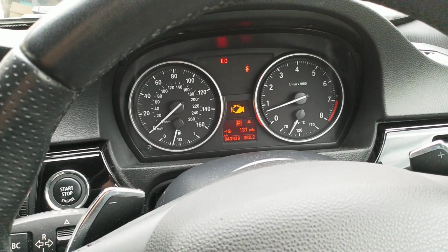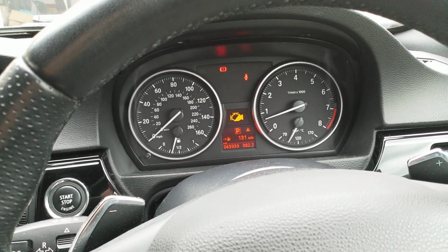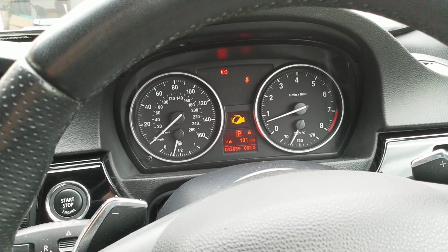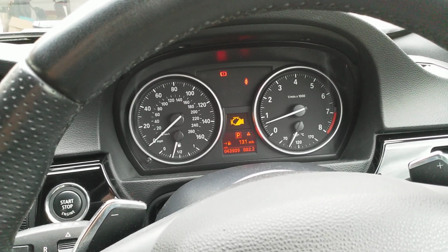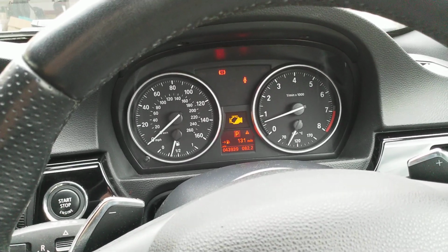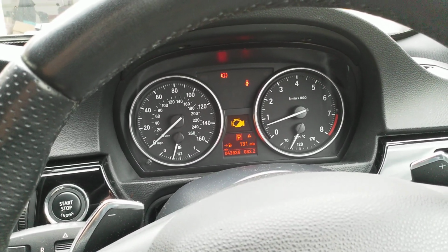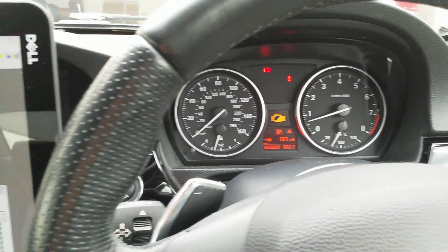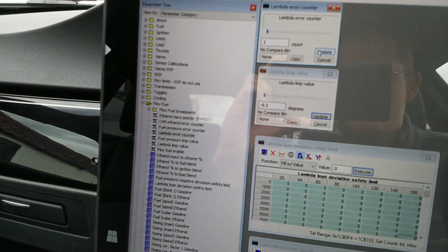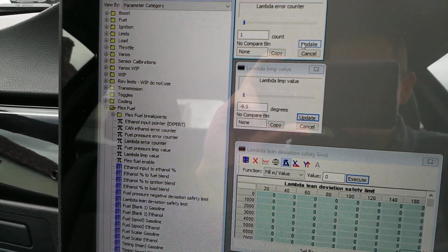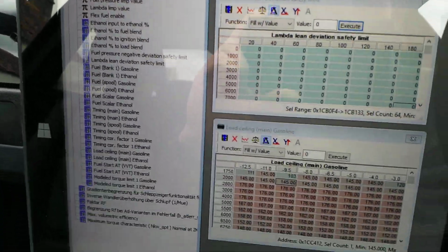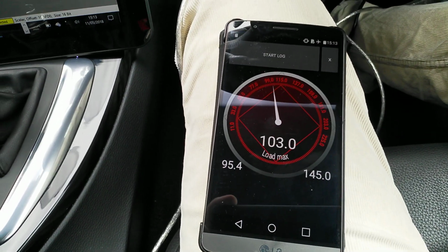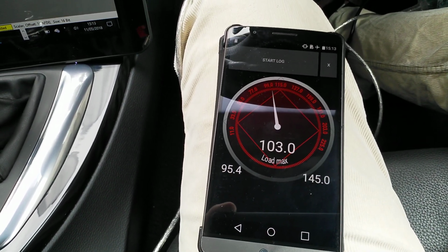Never do live experiments with cars, animals or children, but clearly it was not even slightly leaner until I moved it to a different load zone for a moment. But that's not surprising, sometimes it will stay slightly richer for a few seconds. Anyway, now we're in limp mode again with our -9.5 degrees target, which tallies with what's in load ceiling main, which tallies with the Android phone.